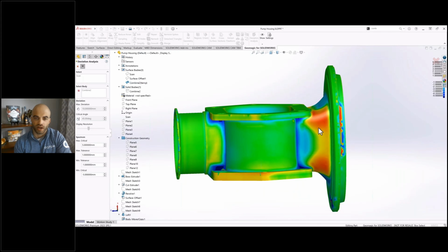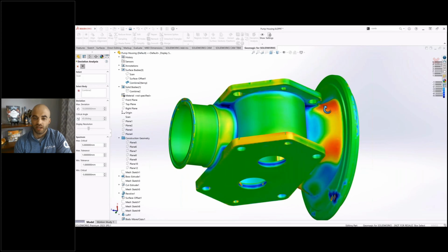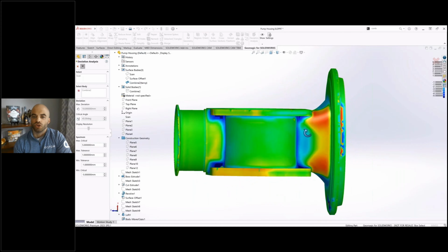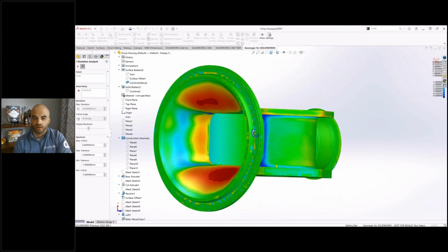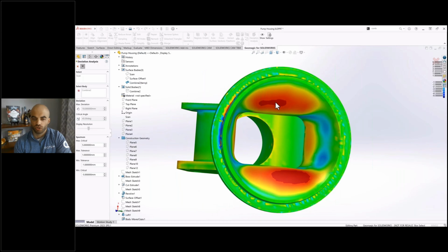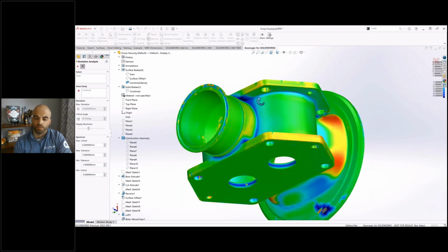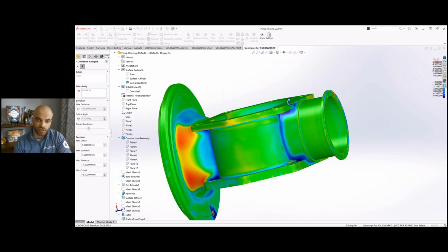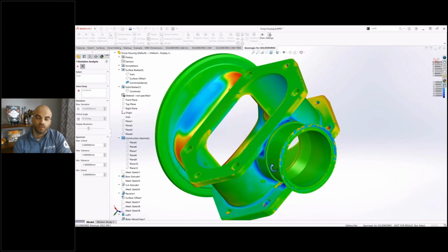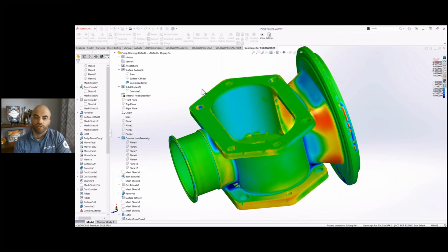And you can see I'm pointing out, obviously we're missing some filleting in there. We got all that blue, but we're seeing some red high spots and blue low spots on the outer surface of that loft. And then we see these two large red spots on the inside of the loft. So these totally need to be fixed. That's another loft profile that needs to be added. But those blue and red spots on the outside of the loft feature, those are what I'm going to focus on, just making sure that the wall thickness is big enough, right?